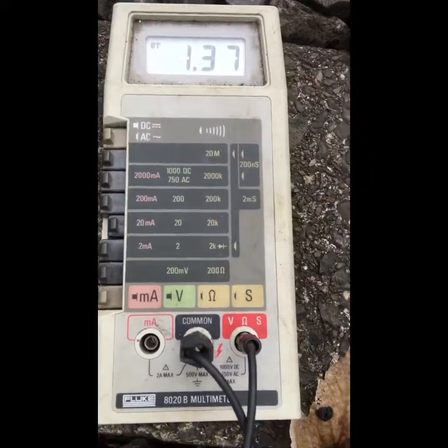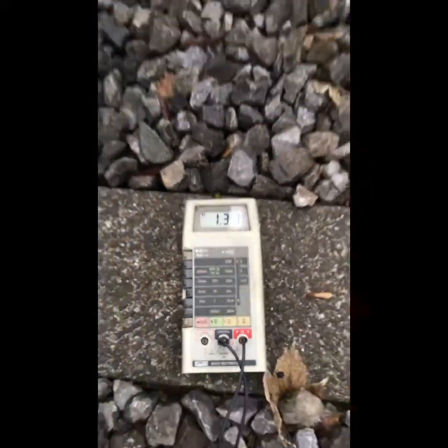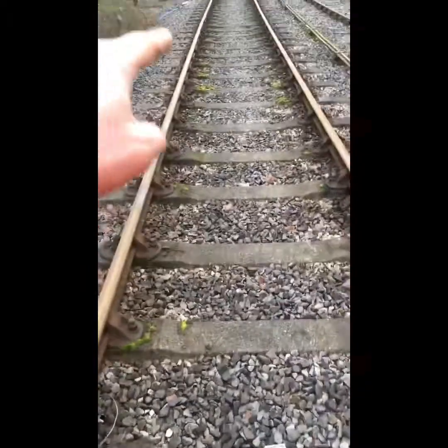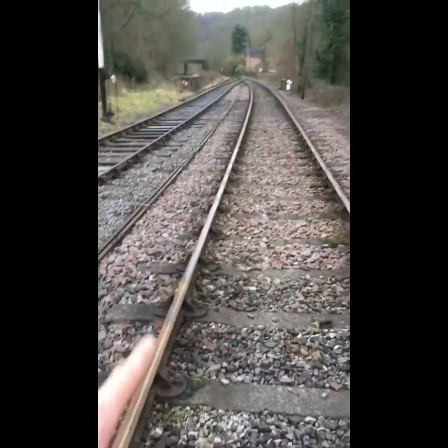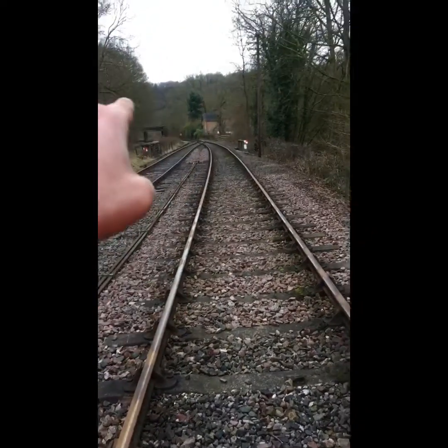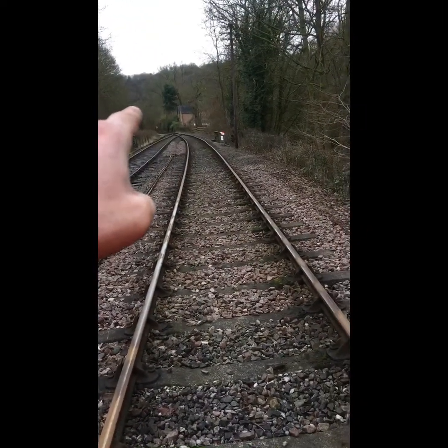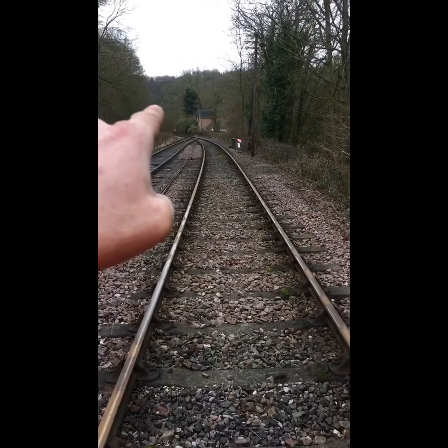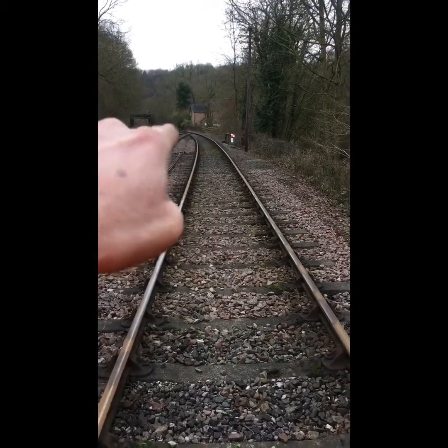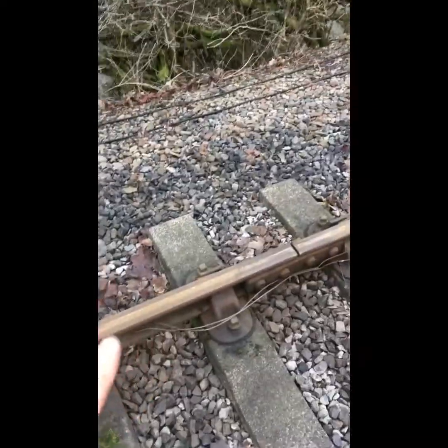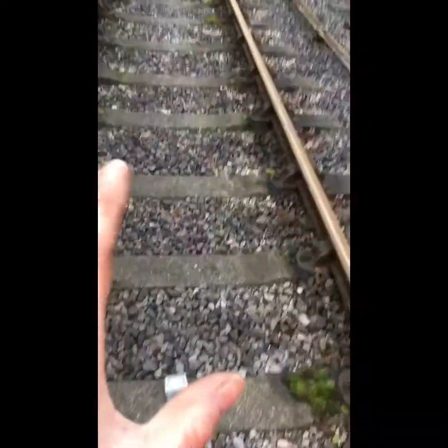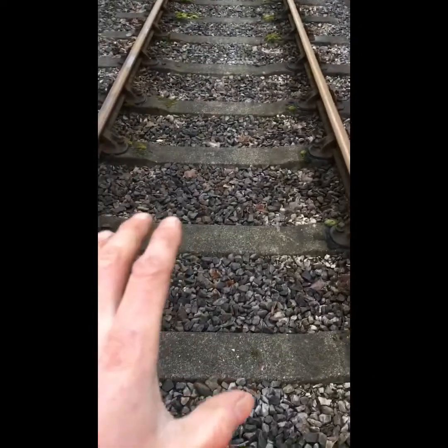And as you can see, we have our voltage upon our track circuit, 1.37 volts, carried all the way through. So the positive is carried all the way through from the feed, and the negative is carried all the way through from the feed, all the way down there. And in there is a power supply which feeds into our track circuit. That carries it down. So as you can appreciate, the setup of the ballast conditions is quite important.